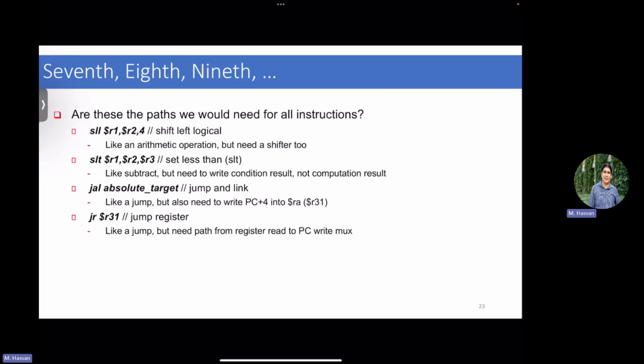In case of an add, it comes from a location. In case of an immediate and load, it comes from another location. And here in this multiplexer also, we said the second source of the ALU, should it come from the register file or from the immediate value, right? And this is a selection line here that we call ALU input B. Now, what type of operation do I do for the ALU? In case of an add, I, and load and store, I'm doing an addition. But in case of a branch, I'm doing a subtraction, for example, right? So you need an ALU op control.